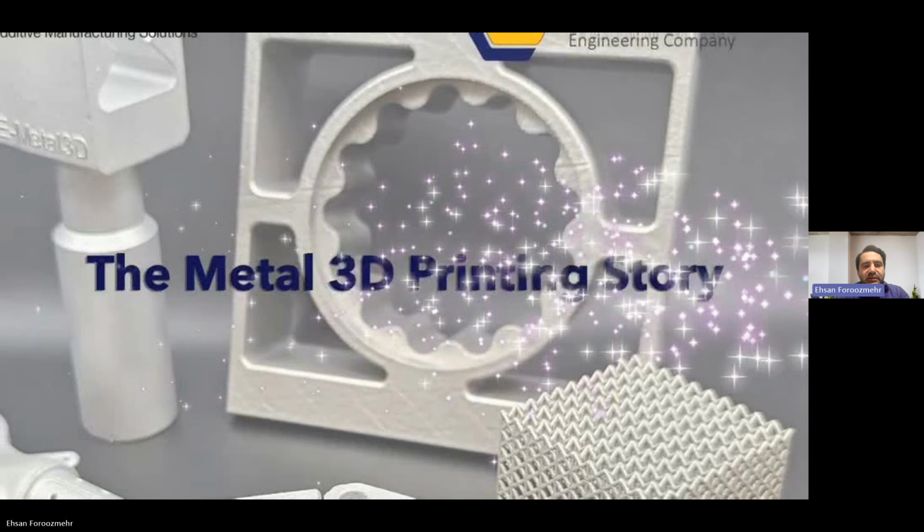Like any other 3D printing technology, everything starts with a CAD file. You may have the CAD file from the CAD software, or you can 3D scan the part and then reverse engineer it. You may need to adjust some dimensions and add excess material for post-machining. The next software is used for designing supports. For reasons similar to other technologies, we need support material to hold up the overhang areas and make sure the part doesn't fall apart during the process.